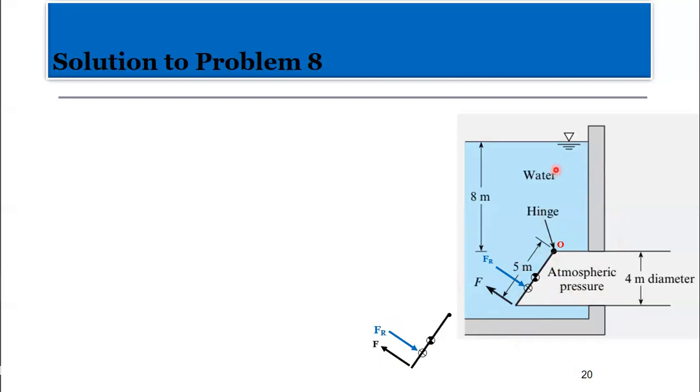Now, if we measure the vertical distance from the free surface to the centroid of the figure, who can tell me that value? What is this? Okay, it's H bar. That's the distance measured from the free liquid surface, here the water surface, to the centroid of the gate. Now, remember the other one is measured from the center of pressure to the free surface, and this is what?